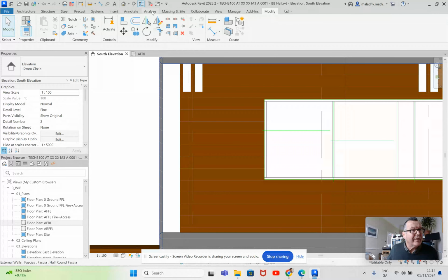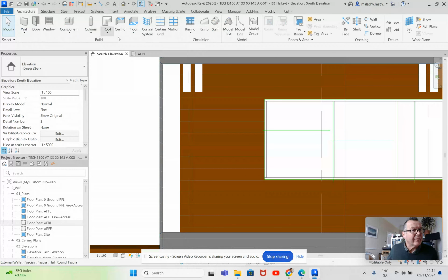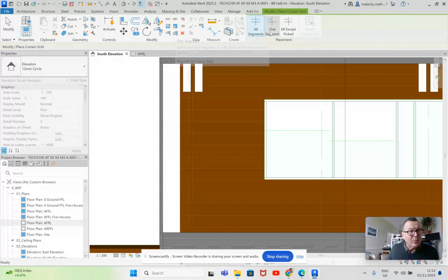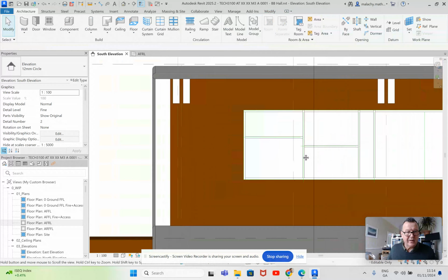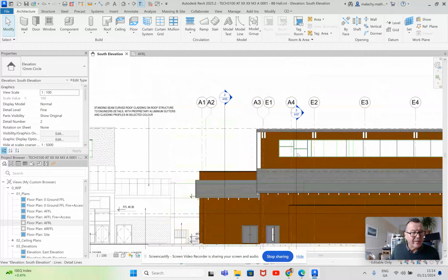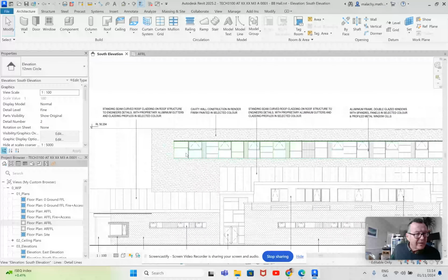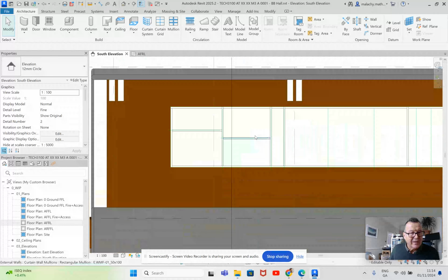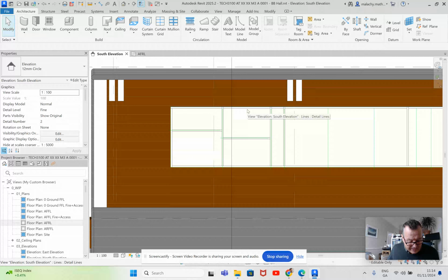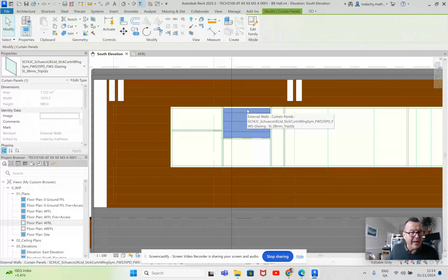And we'll go back to our grid here. Architecture grid. Now we want one segment, right? Roughly there. And one segment. If you don't say one segment, it'll run it the whole way across. All right. Now, so what I need is some sections here. What have we got here? So that's solid, and that's the opening section, right? And it's top hung.